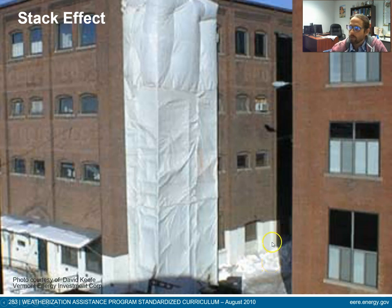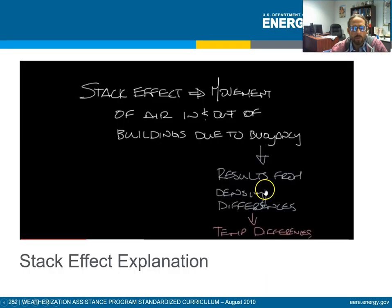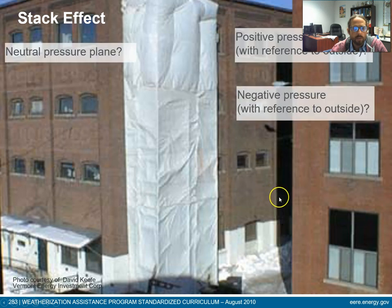This is a really cool picture of actually a stack effect in action. And so you can see this is like a 4-story building here. Looks like it's the wintertime. We got some snow on the ground, and it looks like they're doing some kind of construction here. And so this is covered with a tarp. And you should, if you look carefully, you should be able to see a positive, negative pressure, and the neutral pressure plane. So go ahead and press pause and see if you can find it.